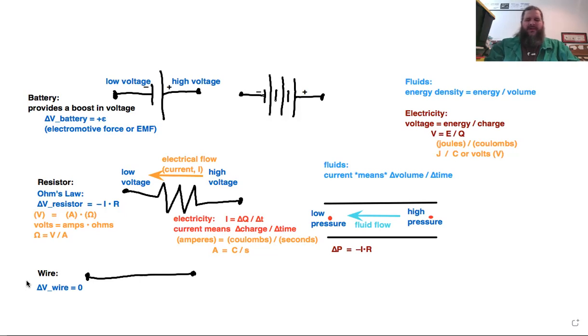So wire can be thought of as a convenient way to transfer voltage. If you have 2 points that you want to be at the same voltage always, connect them with wire, then they're guaranteed to be at the same voltage. This is assuming the wire has zero resistance. Realistically, any wire does have a little bit of resistance. It's just that that's usually small enough to round off to zero.